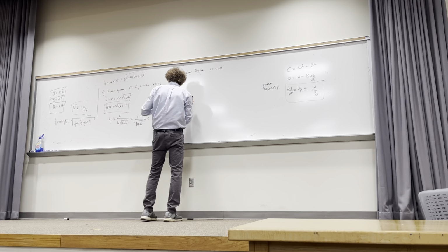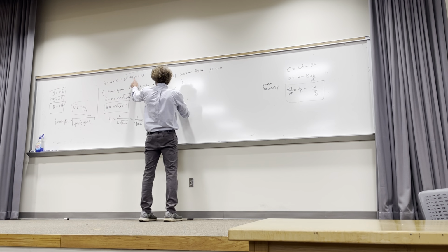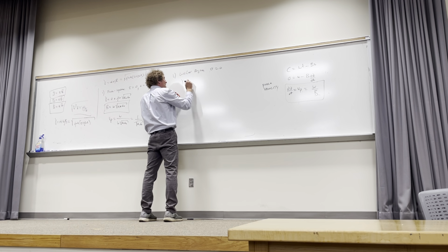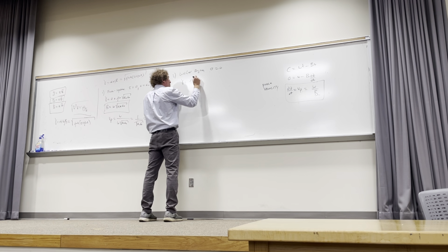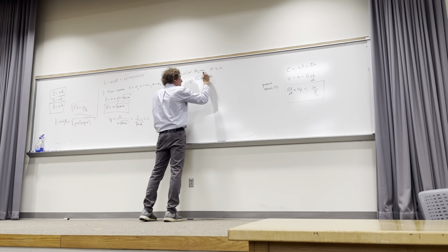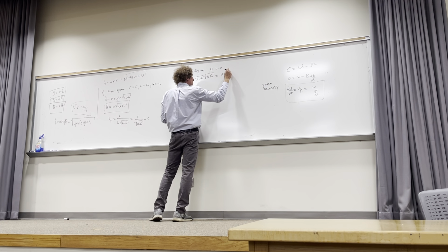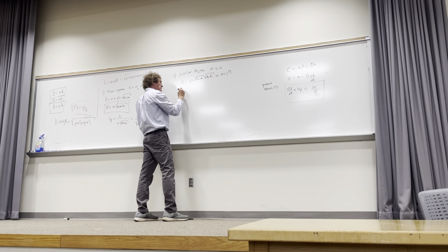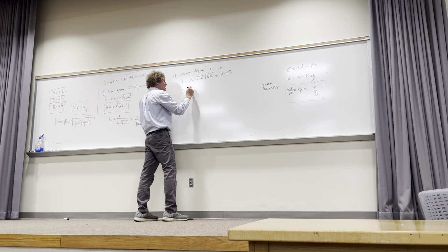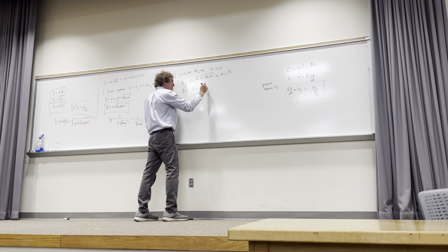Then you can see when I have that equation, gamma is going to be equal to, since sigma is 0, I have j omega mu times j omega epsilon. It's still going to be j omega, but now we're going to have the square root of mu naught epsilon naught times square root of mu r epsilon r. And that's really 0 plus j beta, so beta is this. Beta is simply omega times square root of mu naught epsilon naught times square root of mu relative epsilon relative.